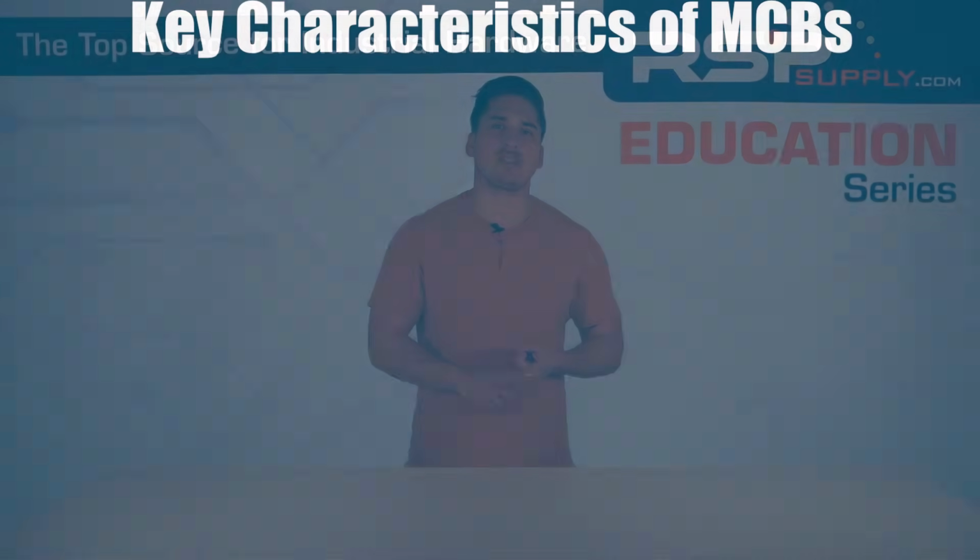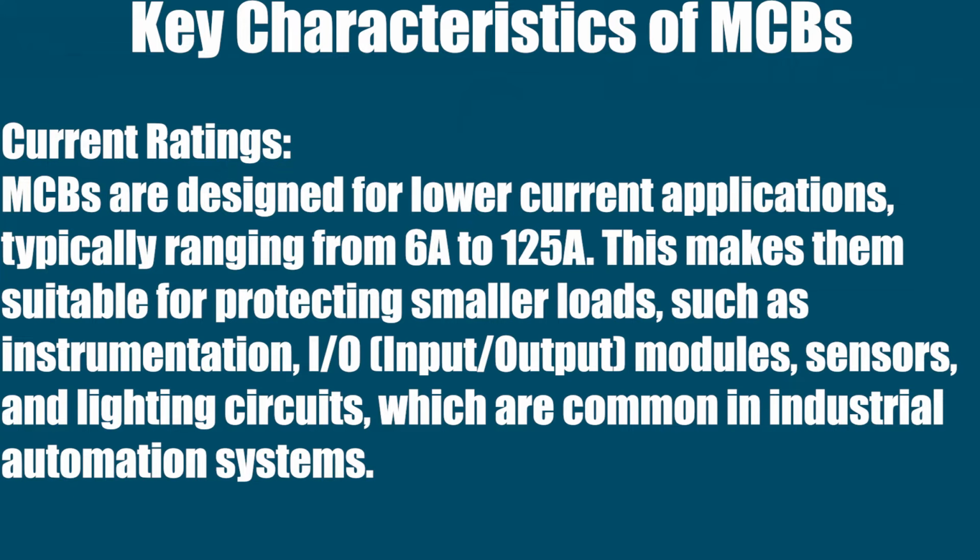Here's a deeper dive into their functionality and importance in industrial automation. Some key characteristics of miniature circuit breakers. Let's talk about their current ratings. MCBs are designed for lower current applications, typically from 6 amps to 125 amps. This makes them suitable for protecting smaller loads like instrumentation, input and output modules, sensors, and lighting circuits. All of these are very common in industrial automation systems.